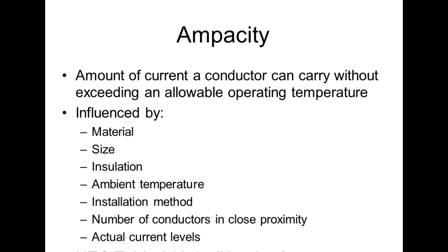And what's the purpose of the conduit? Protect the cables, wires. That's the main function of it. But once you start running a lot of conductors inside a conduit and each one of them is getting warm, that heat is going to build up inside the conduit. So when you look at pulling cables, they specify the number of conductors you can actually pull through that conduit. You never, ever fill a conduit up. Well, I'm sorry, you're not supposed to ever fill a conduit up.